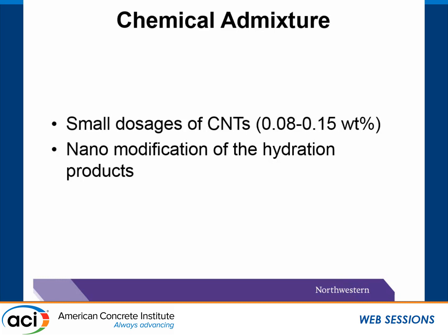Usually microfiber reinforcement is at 1 to 5 weight percent, and our CNTs are at a dosage of 0.08 to 0.15 weight percent to cement. Also, nano modification of the hydration products makes it more similar to a chemical admixture than a fiber reinforcement.